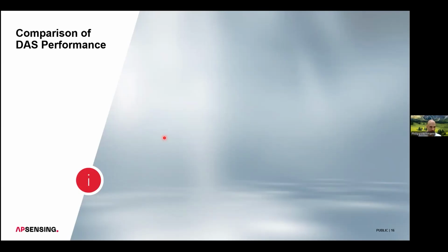Typically, how you do this depends on the situation. Many people already have the GPS coordinates of the fiber cable. Then what you need to do is maybe walk along the fiber cable and tap. I'm just giving rough numbers; it all depends on the application. Maybe you tap every 100, 500, or 1,000 meters on the fiber, generating a signal.